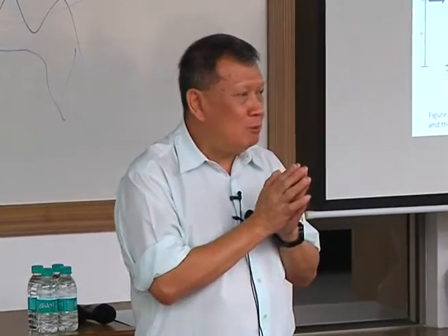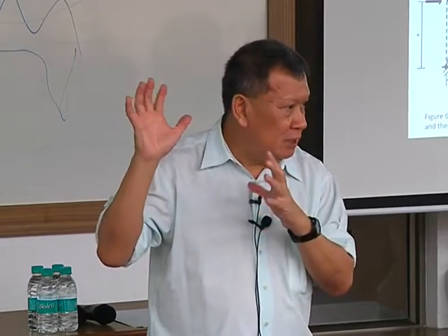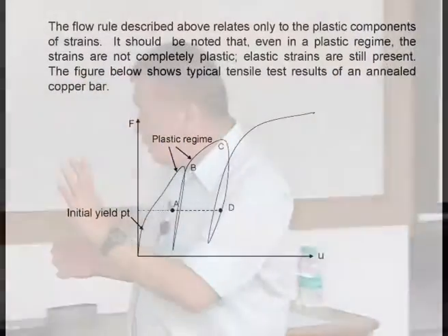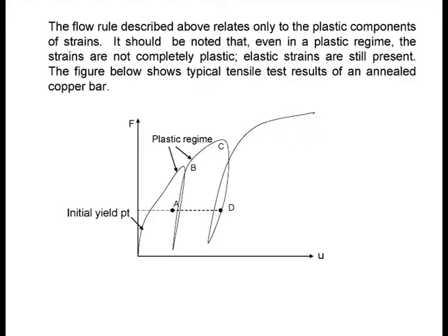So the angle of dilation is the Mohr-Coulomb way of describing the plastic potential, essentially. I will go into detail in the later part of these notes, because that is an important part of the Mohr-Coulomb model that you need to know in order to fully utilize it, and to fully understand the limitations of the Mohr-Coulomb model. Is that okay? So basically, we just leave the flow rule at this juncture for a moment.